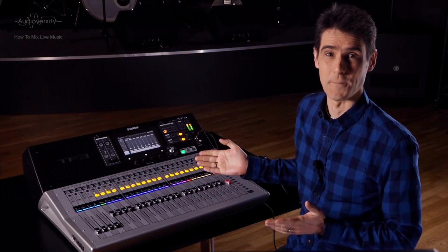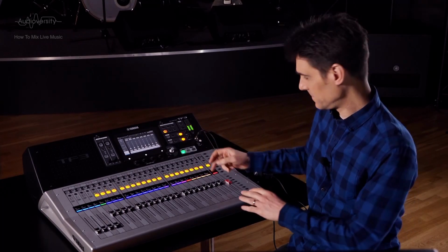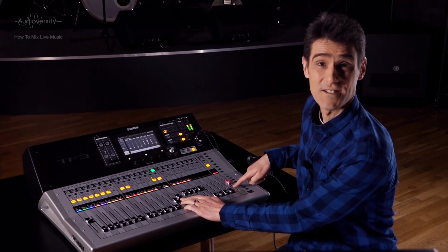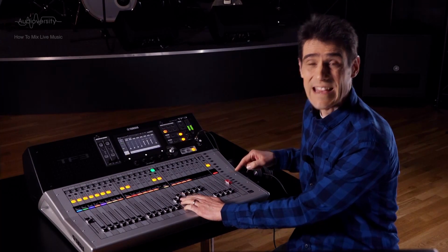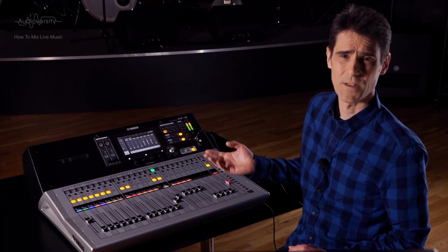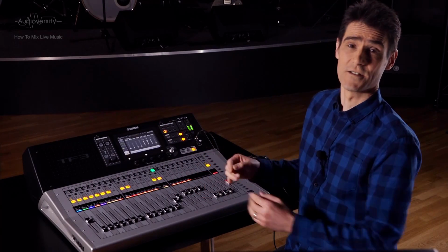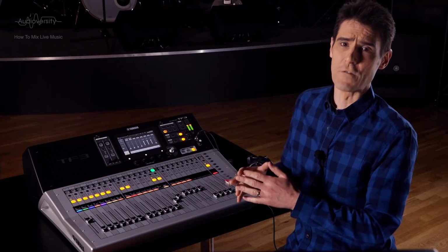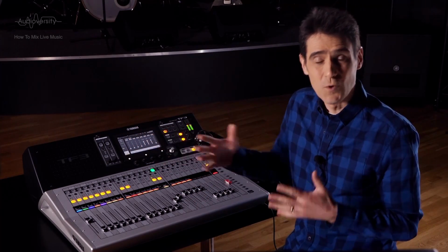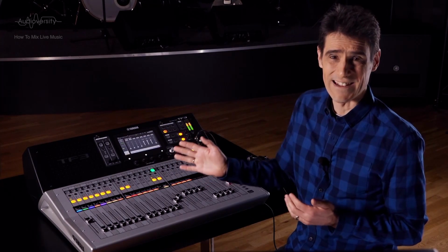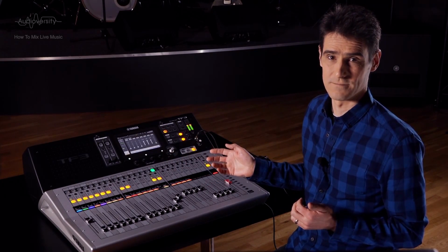On a TF mixer, if you look at the output fader layer, you will see the sub bus as well as the stereo master. You can guess that this is designed to be used with subwoofer speakers. You may have just one subwoofer, or you may have one positioned on each side of the stage. Anyway, the send is usually mono because low frequencies spread widely and it's more difficult to sense the direction of their source. So panning sub-frequencies is futile.